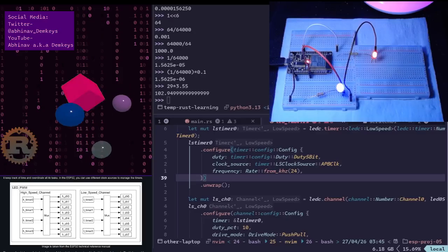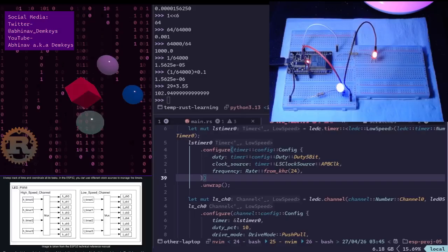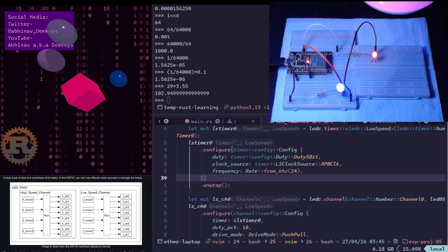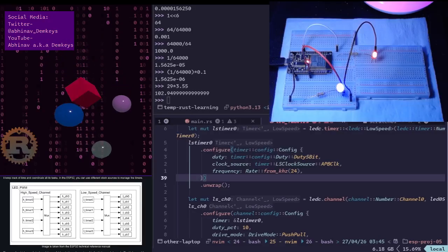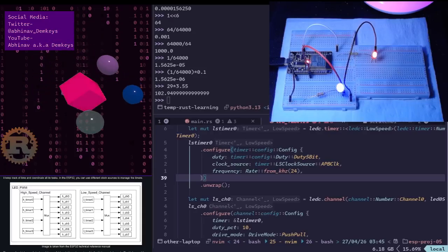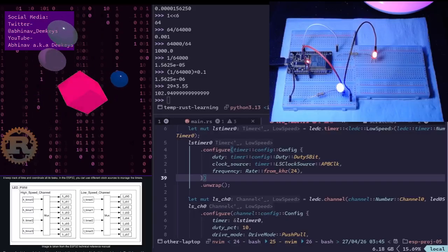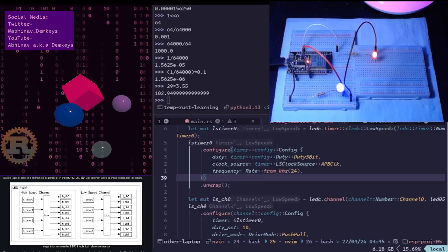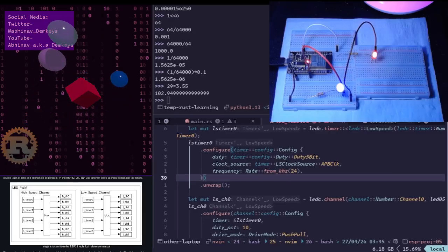Then we have the clock, which is the heartbeat. This is one gotcha you should know. Even if the registers are powered, hardware needs a clock signal, a heartbeat, to actually move. If you put your ESP32 into deep sleep, it usually turns off the high frequency crystal oscillator to save maximum power. If the clock stops, the PWM stops, even if the registers still have the instructions. This is why light sleep keeps certain clocks running, so PWM continues, and deep sleep shuts down almost all clocks. PWM usually stops here unless you are using a specific low power RTC timer.